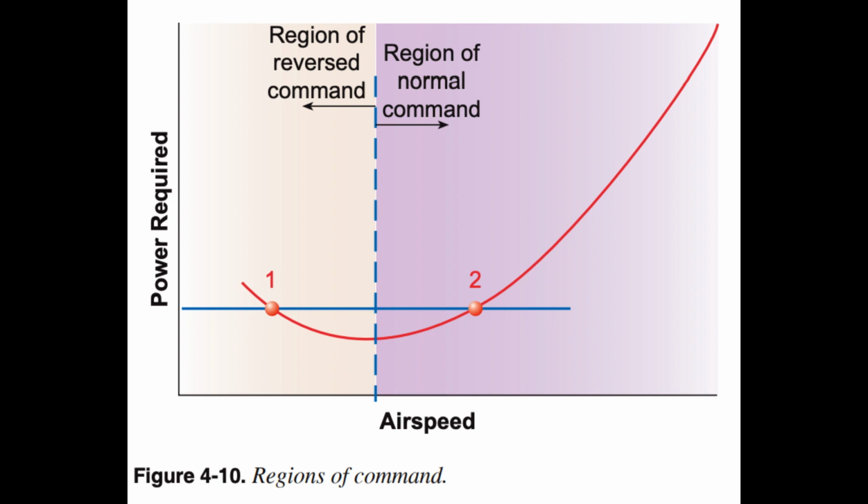Operation in the region of reversed command does not imply that great control difficulty and dangerous conditions exist. However, it does amplify errors of basic flying technique, making proper flying technique and precise control of the aircraft very important. Speed stability, normal command.